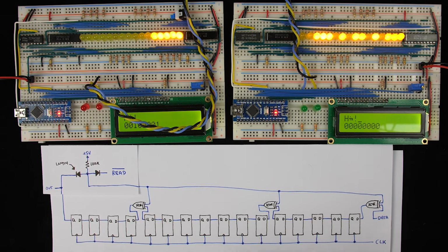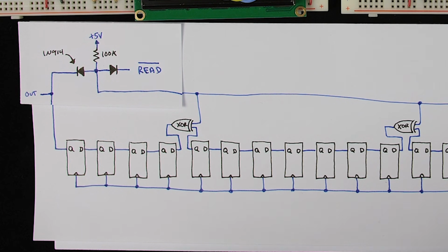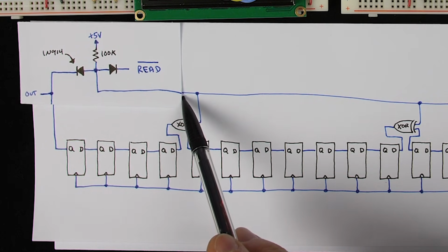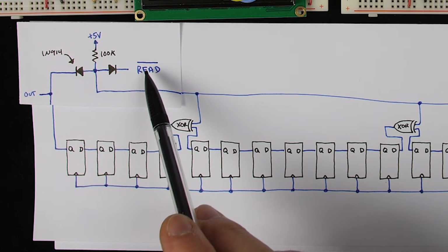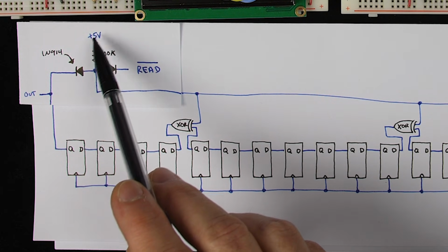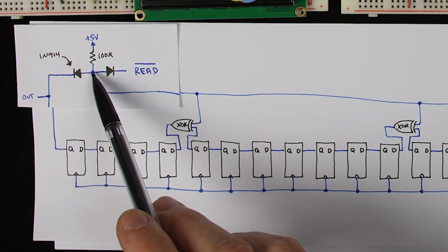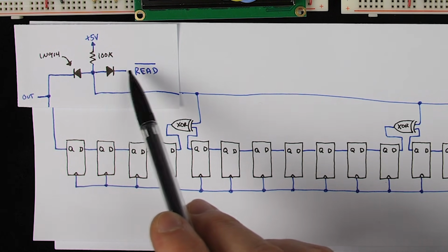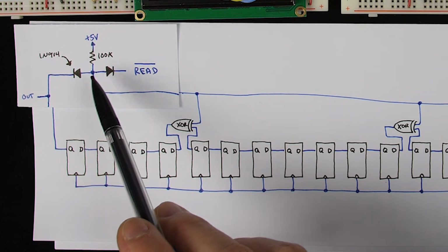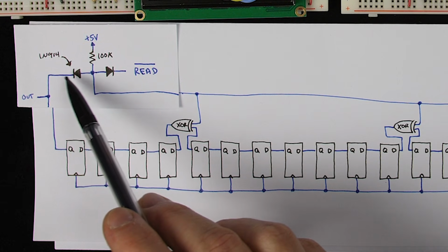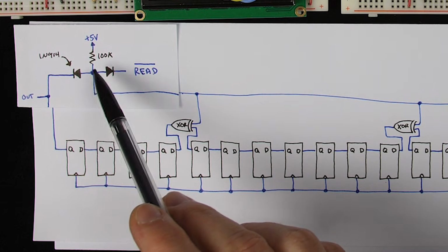Effectively what I'm doing here is creating an AND gate with 2 diodes and a resistor. Just to walk through what's going on, in the normal case, if we're not trying to do that read operation and are just doing the normal CRC computation, then this active low read signal will be high. It won't be active. So if this is high, and we've got this pulled high to 5 volts through a 100K resistor, then this will normally be high right here. Because both sides of this diode are high, there's no current flowing through that diode, so this will just normally be high. And then if the output at the end here of our 16th flip-flop is high, then no current flows through this diode either, and this is still high.